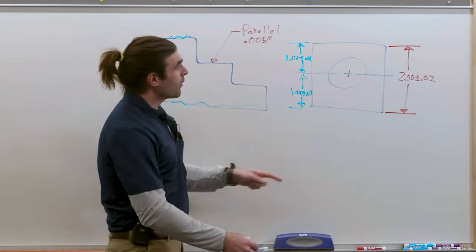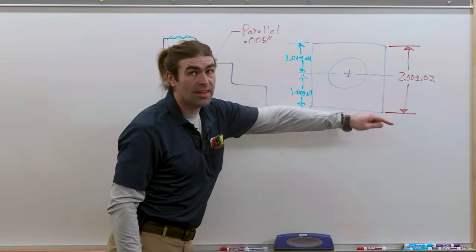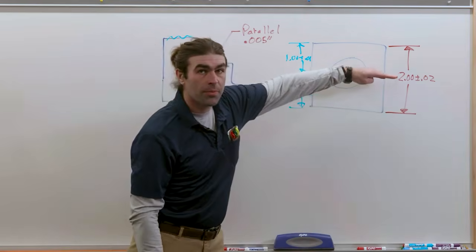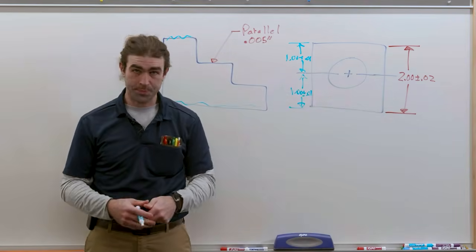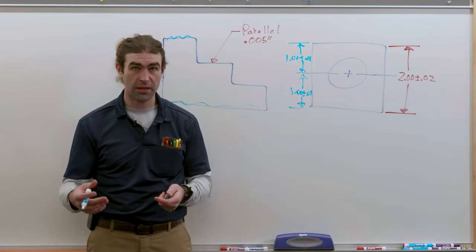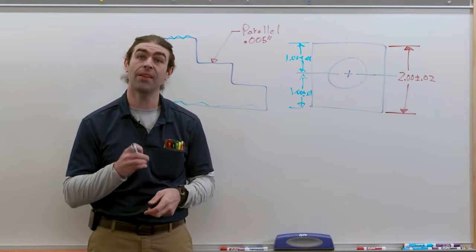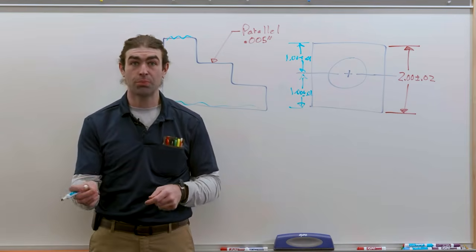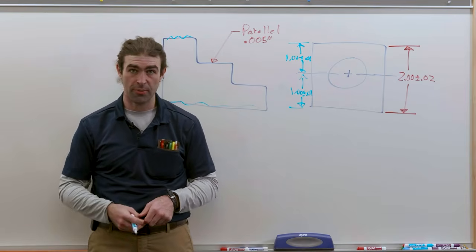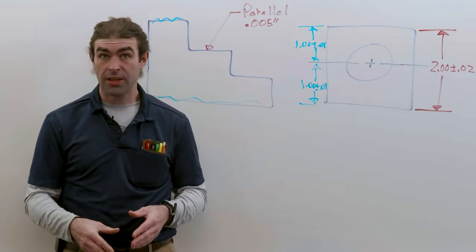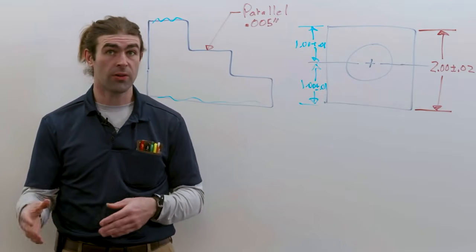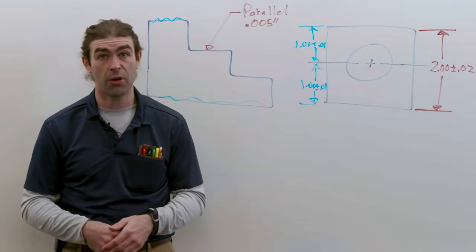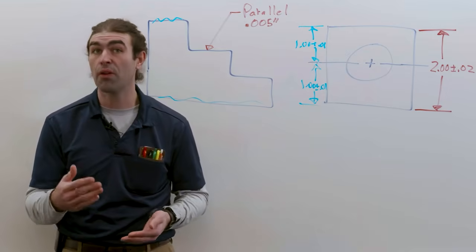What datums do, we can identify this is a datum and clearly state that the center of this part is a center plane datum and then the hole is located from the center of the part. It's all about being explicit about the drawing requirements. Now, we'll talk more about datums as we go through this talk, but this is good enough for now. Datums are places to measure from.